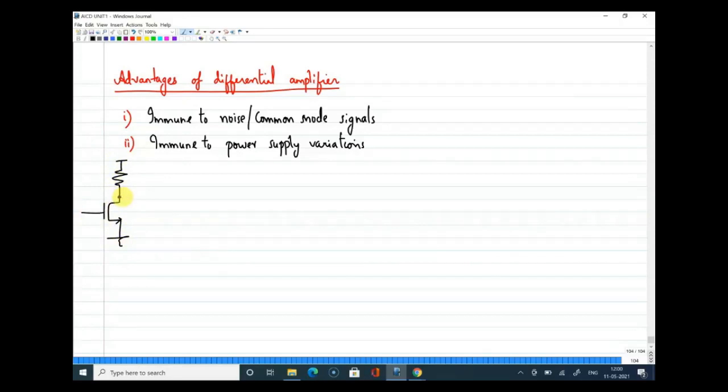So assume that this is an amplifier in an IC at one point of an IC where you have a signal like this. Whenever you have a signal of that fashion, here at the output it will be opposite, because we know that there is a phase shift from gate to drain. That is why we have always written the gain expression for a common source amplifier as minus gm into RD. I hope that is clear.